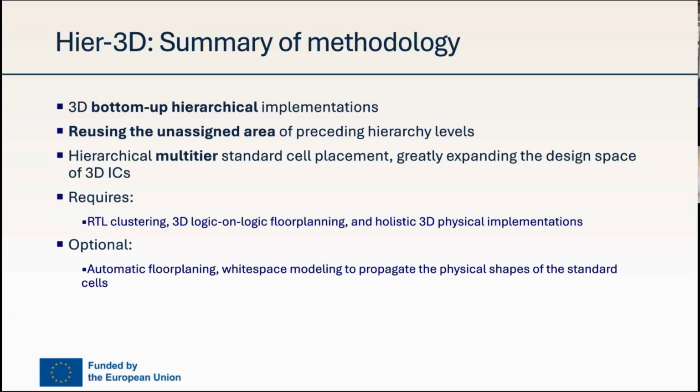If we want to implement completely, let's say, the rough idea that I described right now, you see that some of the elements that we need is first an RTL clustering approach in such a way that we can cut our design in different steps. We want a logic-on-logic floor planning approach that we have to do at the very beginning. And also, we require a holistic approach for the 3D physical implementation that we are implementing using Macro 3D.